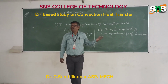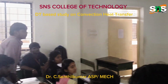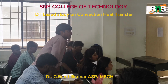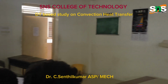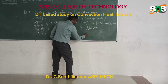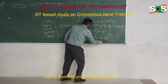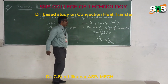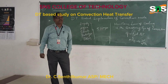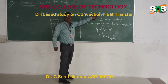Can anyone volunteer to say the equation of convection? Stand up and tell me. Q equal to h A delta T. So here h is the heat transfer coefficient, HTC. Its unit is watts per meter square Kelvin. A is area, delta T is the change in temperature or difference in temperature. So this is the governing equation of convection.